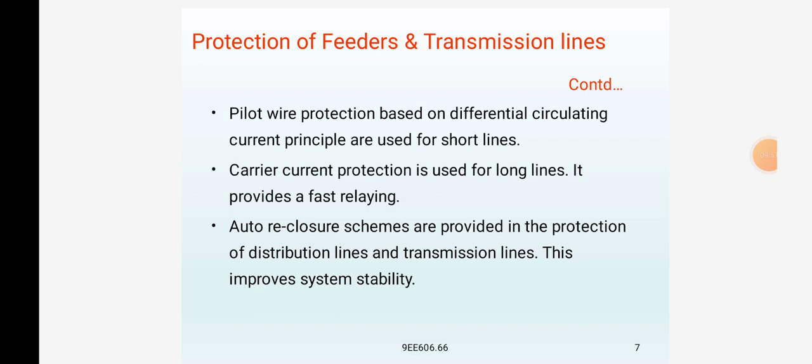In frame leakage protection, it is possible to design a station so that the faults which develop are mostly earth faults, by providing an earthed metal barrier surrounding each conductor in the bus structure.